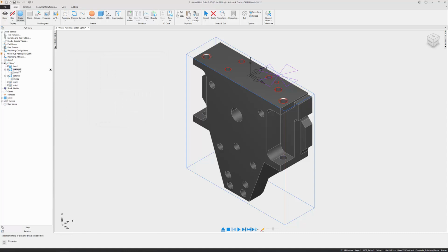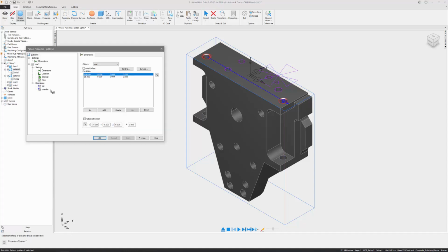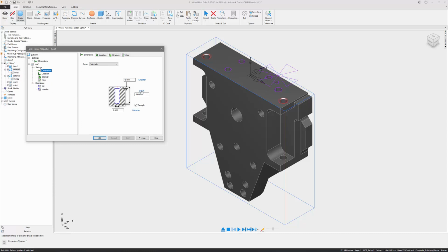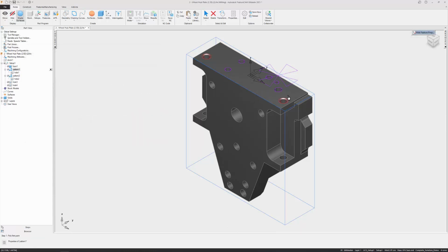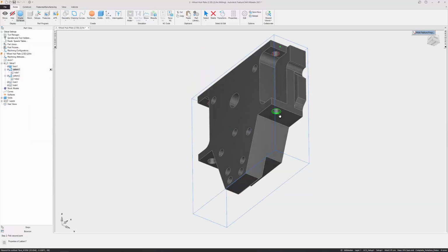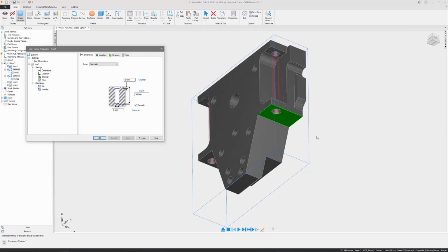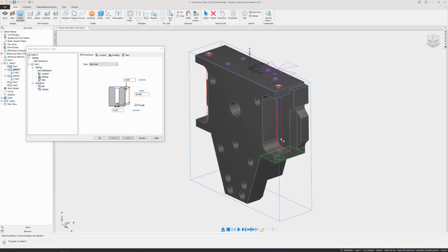So I'll open this hole pattern. And again, this is really helpful, just the power of hole patterns here. We have two holes, but we only need to make this change once. You'll notice depth is in blue, which allows us to pick the depth exactly off the model. So we'll say, let's go from that top face down to this bottom face. And there we go. I like that update.